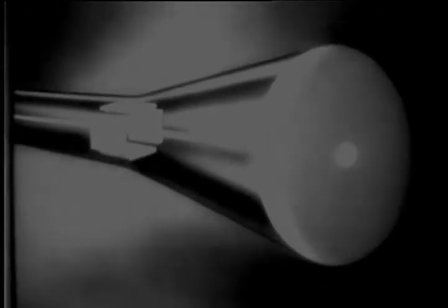However, using a horizontal baseline, this is as long as it can be and still remain on the scope. But what we can do is stretch it out 3 times that length and put it around the edge of the scope. With this longer baseline, representing the same range that the short one did, we can read range a lot more accurately. Here's a typical circular baseline range scope, the J-scope used on the SCR 584. Now that we know why such a scope picture is desirable, let's go back to the electrostatic tube and see how we can get a circular baseline using the horizontal and vertical deflecting plates.